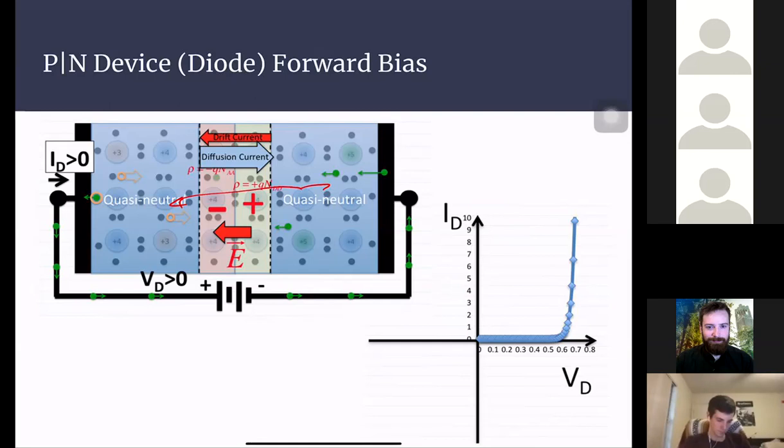But after a certain point, like 0.6 or 0.7 volts, the current jumps because the voltage breaks this gap and pulls electrons out of the atoms and makes them flow, more as the voltage gets more and more powerful. That creates a huge amount of current and sometimes damages your diode. It's pretty important when you develop devices and think of design and things like that.